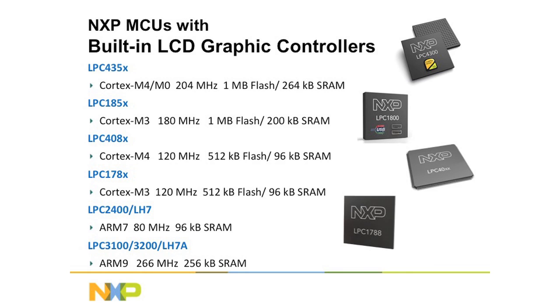The M4 is basically everything the M3 is, plus some single cycle multiply accumulate. The intention was to push into the DSP space a little bit. So it's good for graphics, if you're interested in that, because you can probably do more math processing than you would on the M3. You might take 3 to 7 cycles to do a multiply accumulate on an M3, and 1 on the M4. There are some SIMD instructions, an optional floating point unit, but essentially all the M0 code will run on an M3, and all the M3 code will run on an M4, so there's a lot of reuse of IP. One set of tools will work on all those cores as well. So just a very quick overview there.